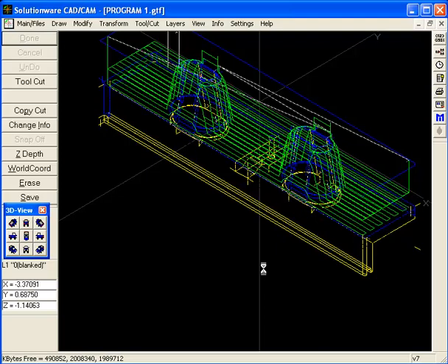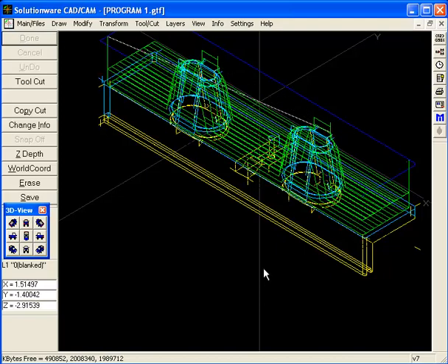And if you recall, I had a Z cut depth on the actual 2D pocket back and forth cut of, I think, negative 1.5 inches, and the actual depth of this surface is about 1.12 or something like that. So it's being controlled by the surface, and we just don't want our 2D cut to be less than that because it will never hit that bottom surface to stay off of. So anyway, there we go.